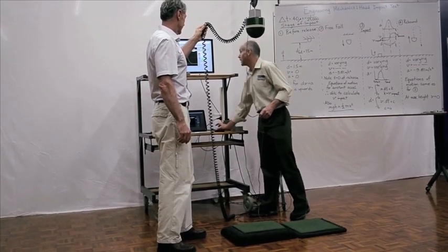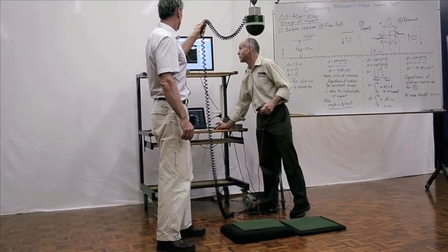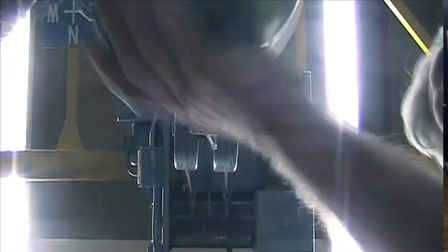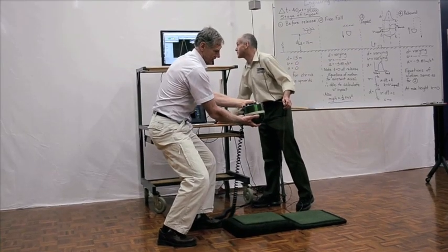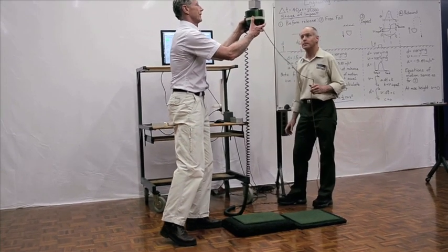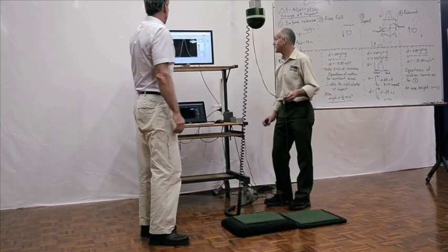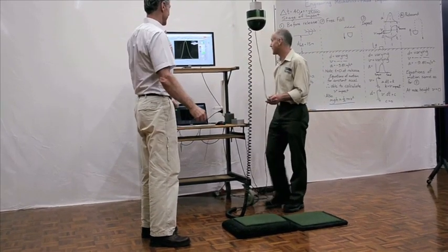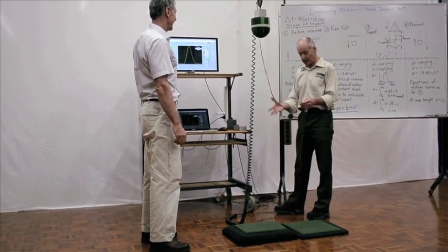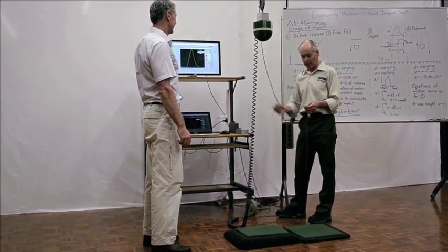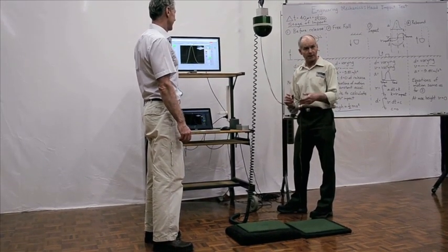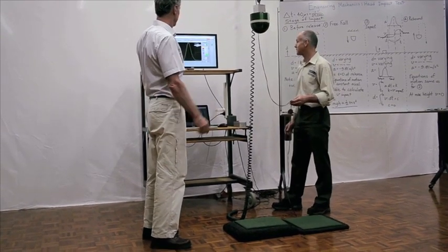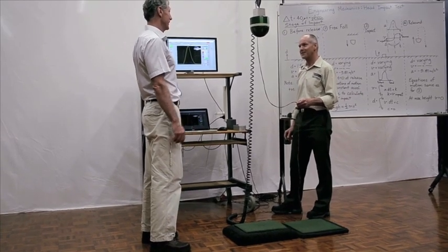Okie dokie. I'll arm it. Computer's armed, it's now ready for the impact data. I'm releasing now. Notice how high it bounced. That bounced to about 660 millimetres. How did it do that, Chris? Well, obviously some of the energy in the rubber was returned to the head form. Some energy was absorbed as heat, some was returned to the head form, which pushed it back up again, just like a spring. But how did the computer know it was 663 millimetres?